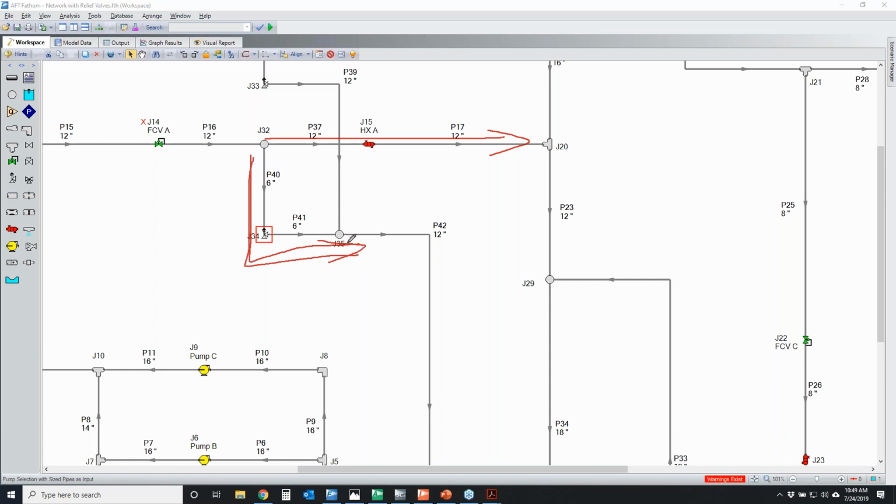When there's flow through your relief valve, it's trying to reduce pressure. The thing about this particular relief valve is it reduces the pressure so well at the heat exchanger by removing some of that flow that your pressure at the heat exchanger drops below your set point.